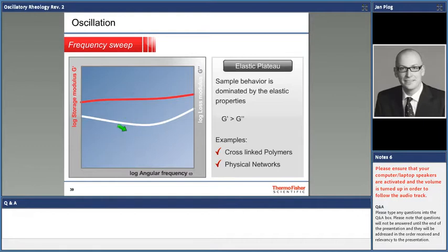However, the important information when you look into gels, for instance, is that G prime gives you the gel strength itself, and it will also give you the possibility to calculate the mesh size, the network configuration of your gel. But in addition to that, the G double prime gives you information on how brittle, on how deformable your network is. Remember, G double prime divided by G prime is this tan delta value. For a given network, tan delta gives you, let's say, the brittleness information.